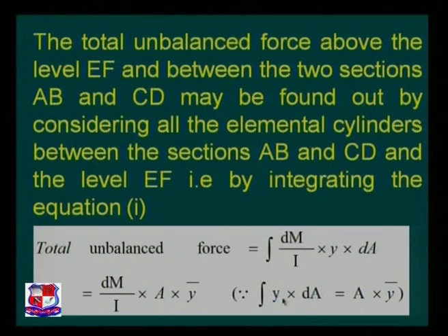That is integration, because dm by I is a constant term which comes out of this integration sign. So integration y dA is nothing but the area into y bar. So we achieve total unbalanced force is equal to dm by I into A into y bar.